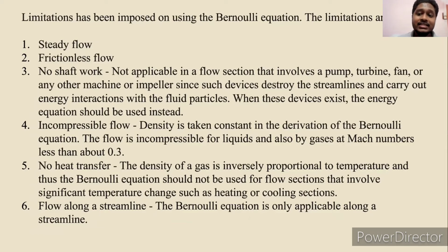There are certain limitations imposed on using Bernoulli's equation. So the limitations are, first of all, the flow has to be steady. Second, the flow has to be frictionless. Third, there shouldn't be any shaft work applicable in the flow.